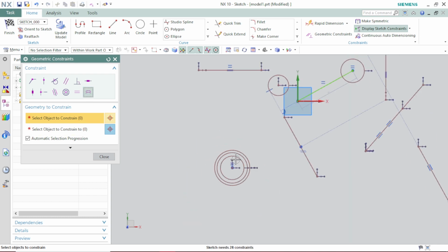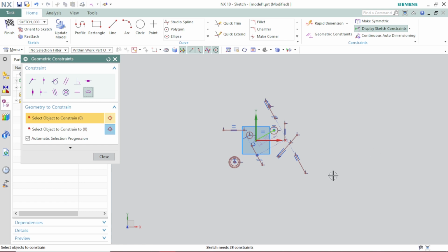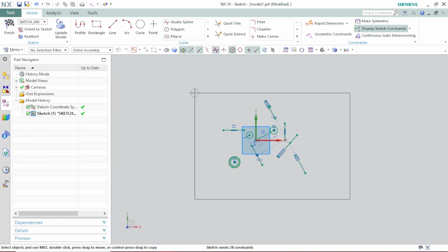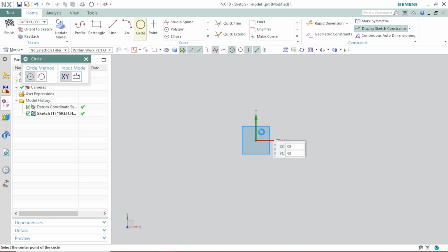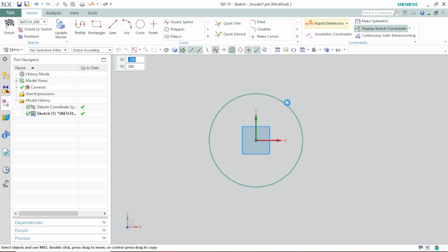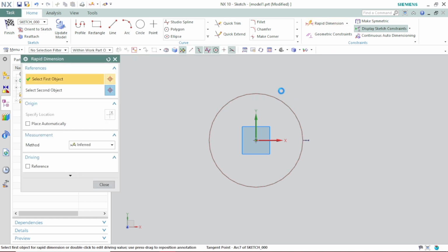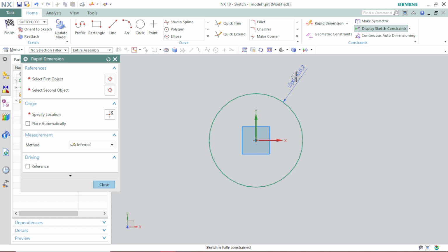Now if your sketch is not defined, okay, you have not user defined your sketch, then always your second selection will be marked as your change. For example, let's observe here, I am selecting one circle and I am defining this circle with specific dimension here.